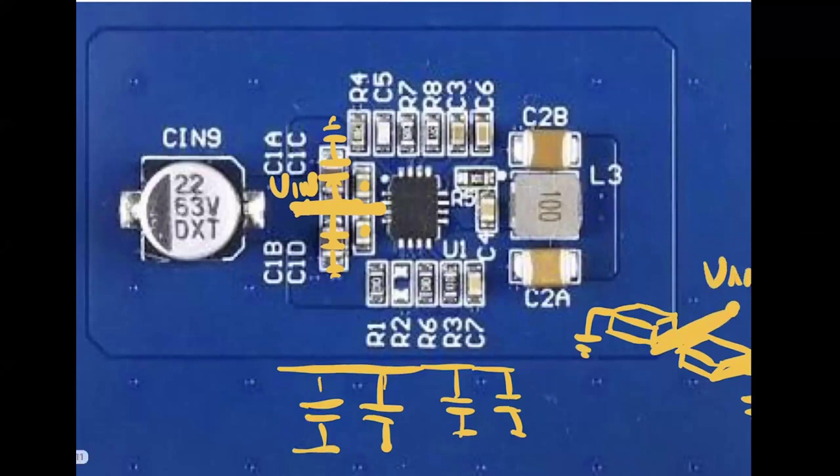The idea is that the current that you are injecting in the device that is switching has opposite directions, and the magnetic field is canceled. If you repeat this idea in the input for the 4 capacitors and in the output for the capacitors in the output circuit, you will have exactly the same idea. This is one of the most important things.